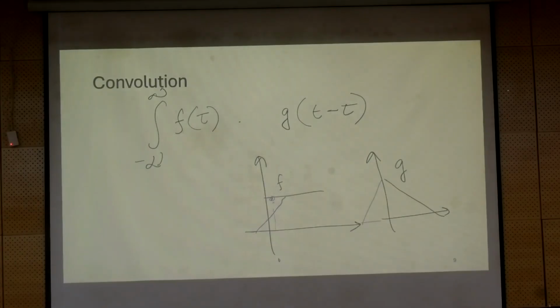So this is a convolution in time domain. Interestingly, when you do convolution in time domain, if you look at it in frequency domain, it is equivalent to just multiplying the signals in frequency domain. If you do a frequency transformation, f is converted into frequency domain, g is also converted into frequency domain, and you just multiply the two signals. That is equivalent to convolution.